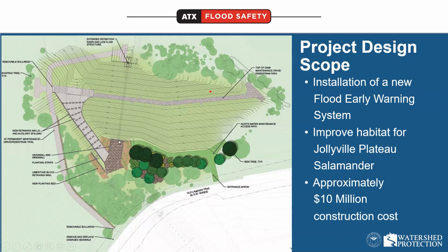We're replacing the spillway, the service spillway. We're installing the new emergency spillway. Here's the plunge pool that I mentioned. This area we're going to use for staging during construction, keeping some of the materials. Once we're done, we're going to plant back some trees so that we can keep it in a more vegetated state. However, we are required to, like I mentioned, maintain the dam without trees as well as a buffer, because that allows for maintenance and for inspection of the structure.